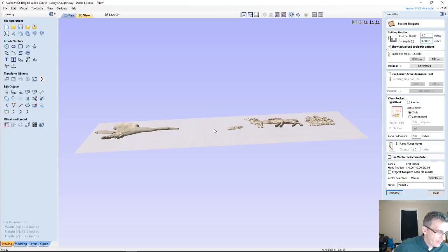If I'm touching off on the top of the material or touching off on the bottom of the material, the depth of my pocket, my model Z-plane, is 0.3037. But because I am referencing off the bottom of the material, the top of my board is thought of as 3/4 of an inch, 0.75. My model Z-plane from 0 is 0.4463. Going from 0 to 0.4463 is that 0.3037.